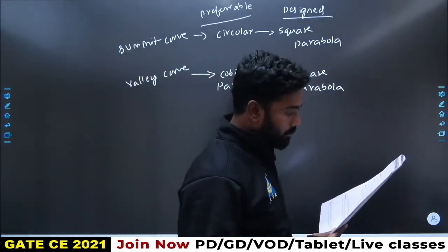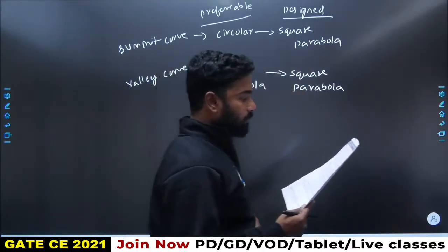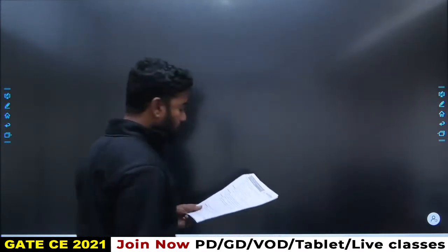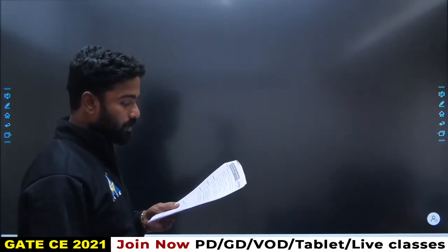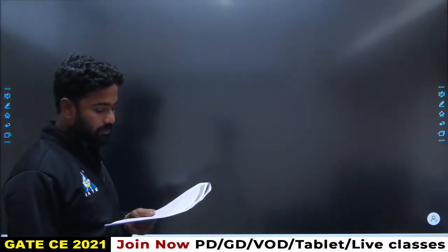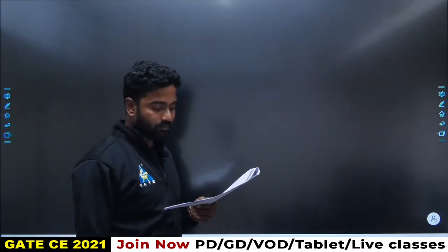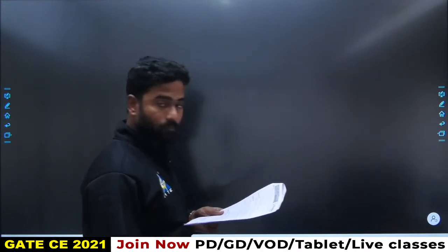There is a traversing question. Traversing is carried out for a closed traverse PQRS. The internal angles at the vertices P, Q, R, S are measured as 92 degrees, 68 degrees, 123 degrees and 77 degrees respectively. If the forebearing of line PQ is 27 degrees, the forebearing of line RS is, right?